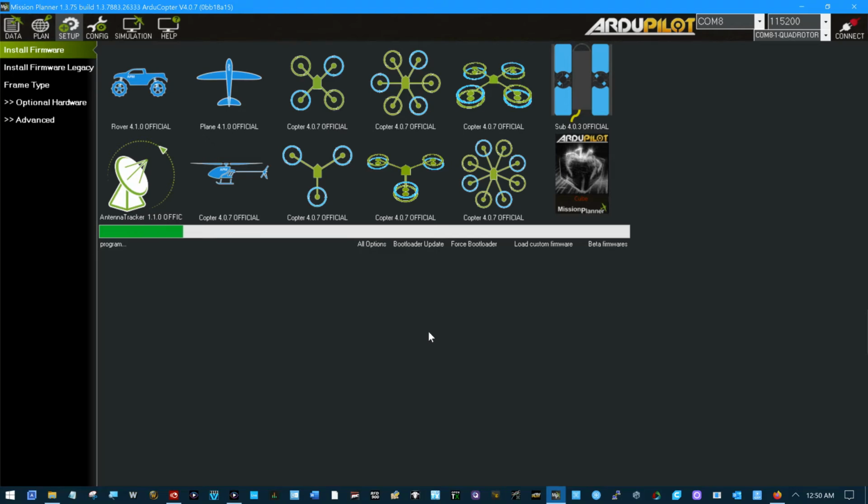But I'm still going to show you a way to calibrate the ESCs when you run into any situation like this. The only thing the ESC needs is to be put in programming mode on power up, and then be able to see the high throttle and low throttle position.